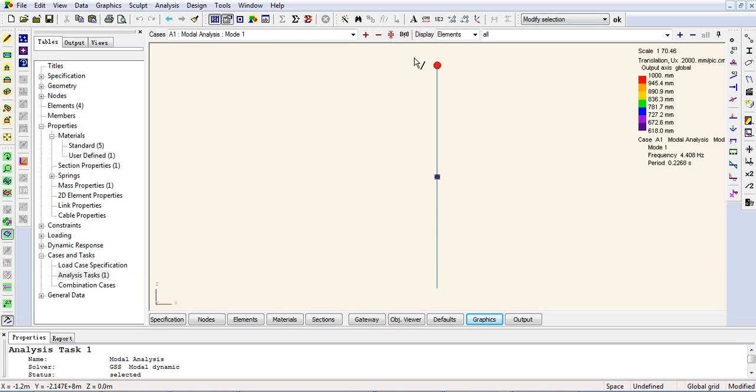And if you are not sure about whether the value is right, you can use the select for animation tools on the left hand toolbar and select them. You can see here is 1000, here is 618, and at mode 2 here is 618, here is 1000. Okay, so then you can be sure about the value. Okay, that will be all for the model analyze GSA tutorial part.